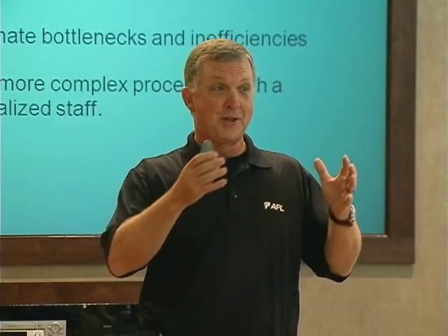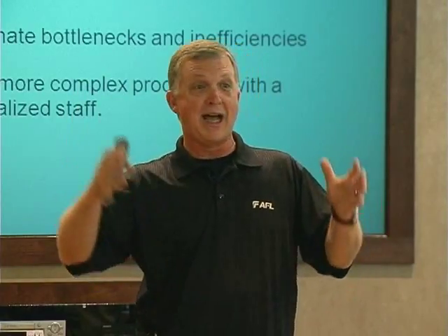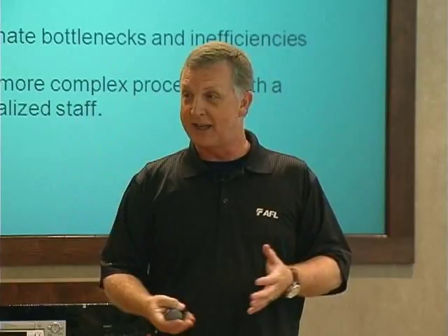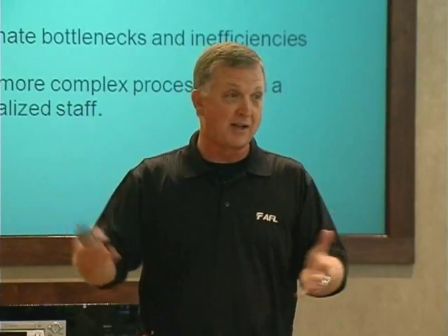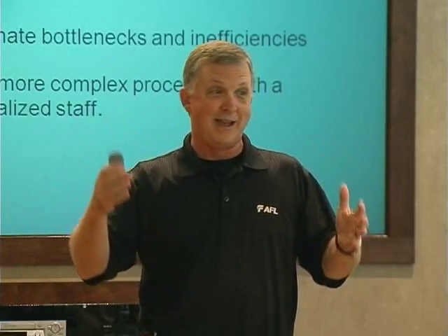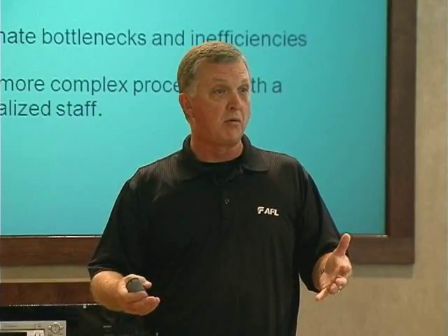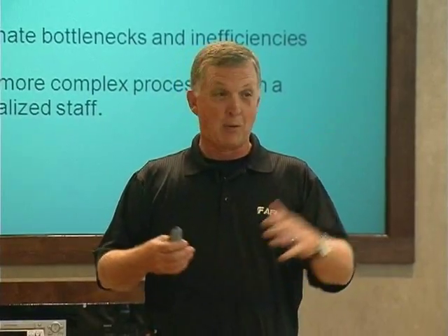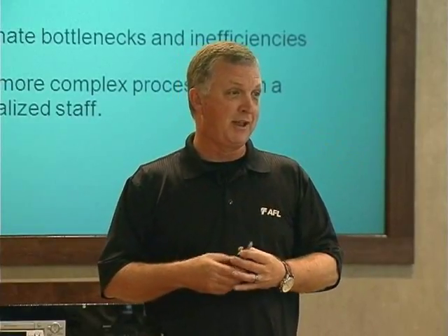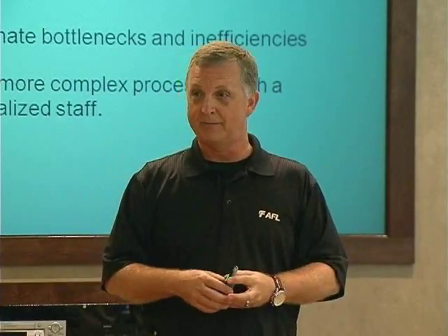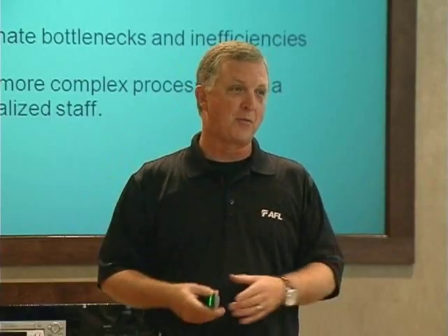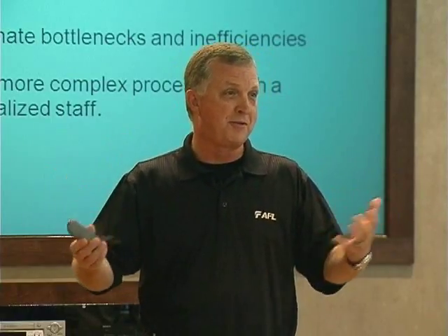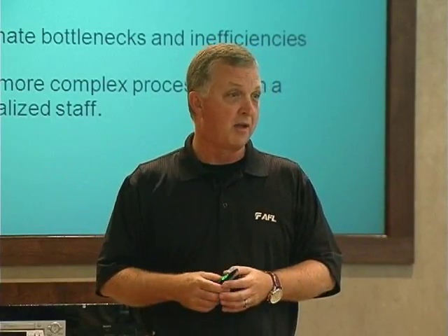Because if there's a lot of load on the line, one of these days like today when it's going to be 100 degrees and everybody's got the air conditioners on and everybody's pulling a lot more load than normal, guess what? The voltage level has a tendency to go down. And I want to know what that voltage level is, especially if I've got trouble spots. And you can kind of do the math and work backwards to the current flow. You may be more interested in voltage or current, but you can measure both of those.